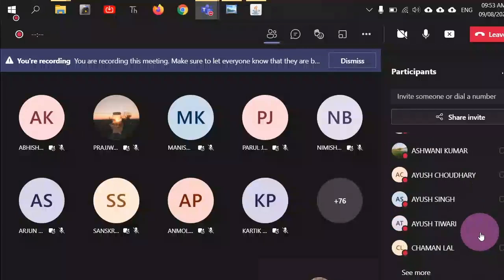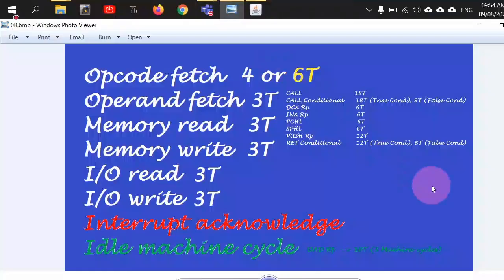Okay, so in the IN command, we write after that some address. IN itself will consume only 1 byte and the address will also consume 1 byte, because the address can have a maximum value of FF, so it can consume a maximum of 1 byte. So how many bytes will be consumed by the IN or OUT statement together with the address? 2 bytes will be consumed.